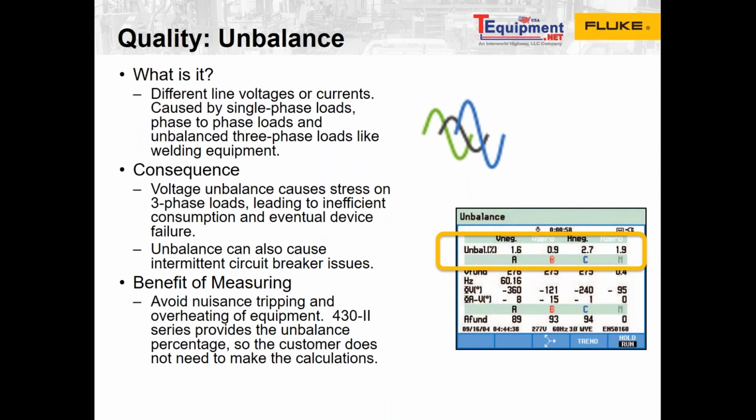And so really you don't have an accurate picture of your power quality by using single measurements at a time, especially if you're trying to track down unbalanced issues. Kind of a rule of thumb, and I don't like rules of thumb because I'd rather know the reason why, but this is just what I've been told, is basically any voltage unbalance greater than 2% is problematic for, I think, any electrical system.